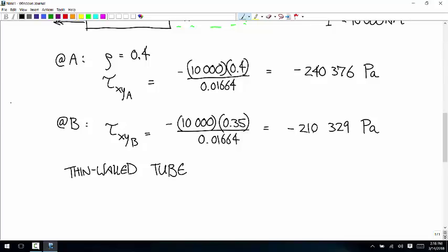So it's not great, but as far as just trying to get a ballpark figure that you could then compare to finite element results, depending on your application, if that's the only way you can do a calculation, it might not be so bad. In this case, we have a better way to do the calculation. But the point of the thin-walled things is most of the time you're not lucky enough to have a circular cross-section. And if you have a tube that's not a circular shape, there's only one way to do this calculation. And you have to know whether you can trust treating it as a thin-walled tube or not. You know what I'm talking about?